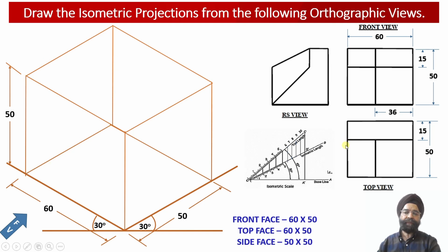So from the left hand side face of the solid, there will be a vertical web which is going to extend from the front side, and the thickness of this web will be equal to 24 millimeter, and this web happens to be vertical up to a distance of 35 millimeter from the base, and then this will become inclined towards the top surface of this particular solid over here.